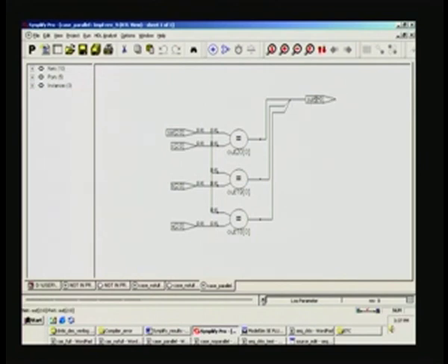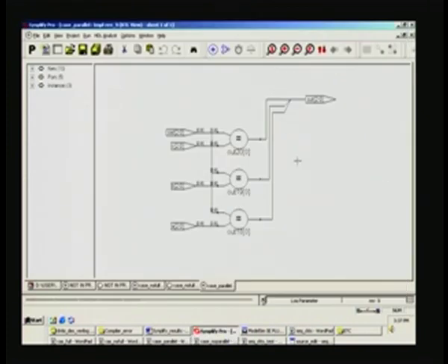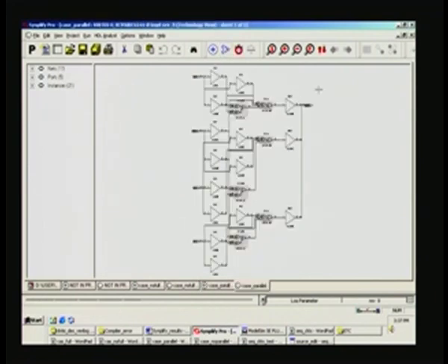So, that is governed by the code that you have already written, that is here, right. This is not plain there, and so is the case for select equal to B, select equal to A. So, it is primarily this, and this is the technology view. Once again you see all the inputs have I buffer and then outputs O buffer, and then you see LUTs being used here: 1, 2, 4, 6 LUTs are used. Once again these are all input buffers, and this is a parallel case.